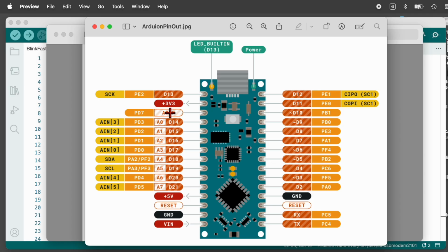The notation 3V3 means 3.3 volts. And we see a similar notation with resistance, like 3R3 would be 3.3 ohms. We've got ground and reset pins over here, and these are electrically connected to the other side as well, just for convenience.